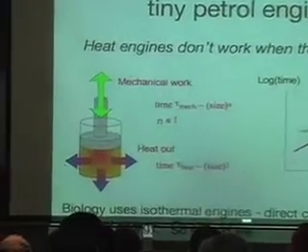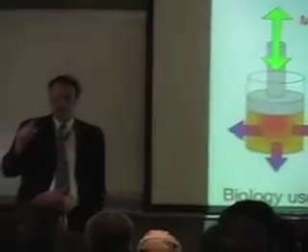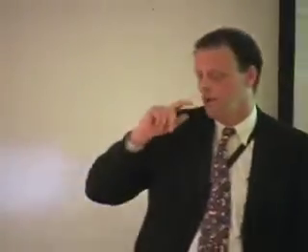according to the Carnot limits. Now, as you make something smaller, the length of time that you can sustain a temperature gradient gets smaller, because big things get colder more slowly than small things. Small cups of coffee get colder more quickly than big cups of coffee. So the time that you can sustain the temperature gradient actually scales as the size squared, because it's a simple diffusion process. So as we make our heat engine smaller, we have to run it faster. Otherwise, the heat will have dissipated away from the explosion in the cylinder before we have a chance to get the mechanical work out. But of course, there's a limit.